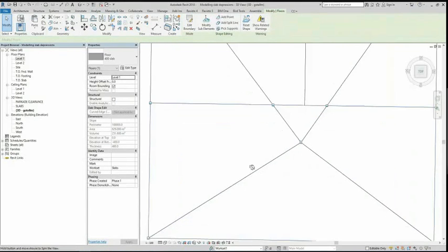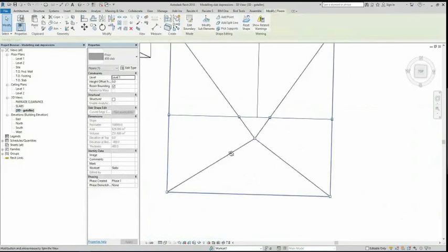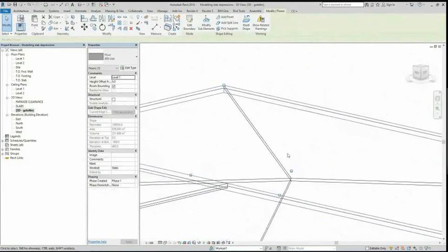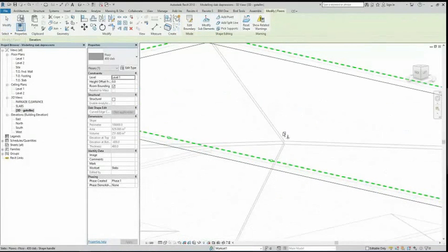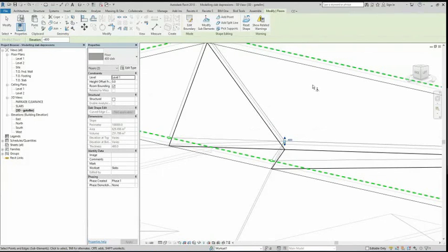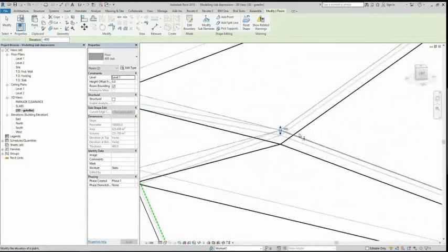All right. So what I'm going to do is start with the big slab first, and I'm going to just go back to 3D view. You need to do this next step in 3D view, or sorry, at an angle so you can see the lines of the sacrificial slab. So I'm going to select, or still have selected, the thicker slab, and go to modify sub-elements. I'm going to click the area drain one first, and you'll see here that because I'm in 3D view, it'll let me just drag that elevation. So I'm going to actually just type it in. I didn't mean to go 200 high. Negative 400. So now I am matching, or should be matching, the sacrificial floor element.